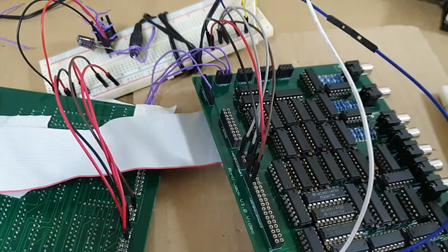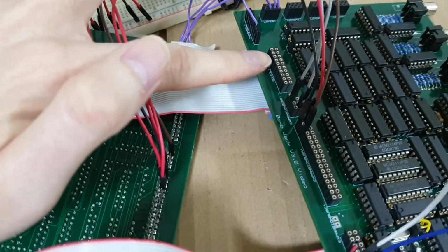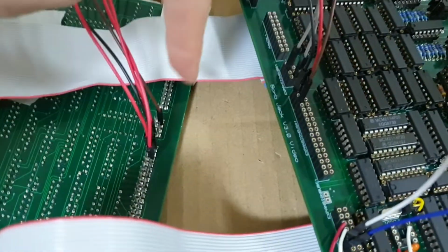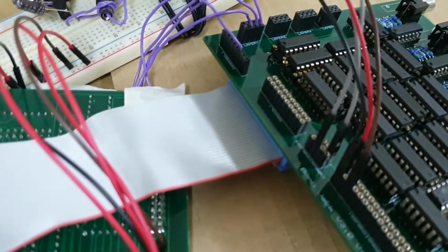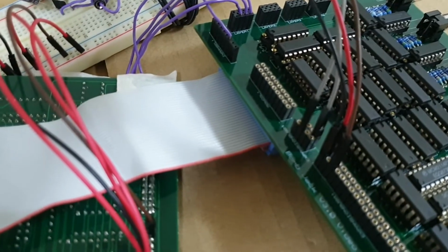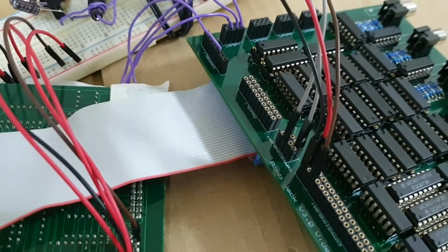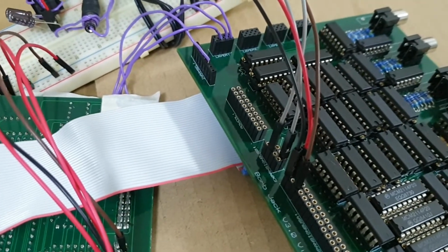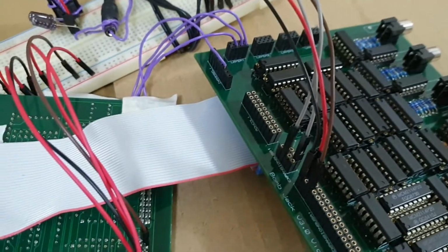So, small little status update. As you can see, I've disconnected all of the wires here, and likewise here. I have not connected the other end. This is just the video generation board on its own. This is to basically check that there are no shorts on the cable or anything else wrong with the socket, because I had to make these by hand, and I crimped them together with pliers because they require quite a lot of force to put together.